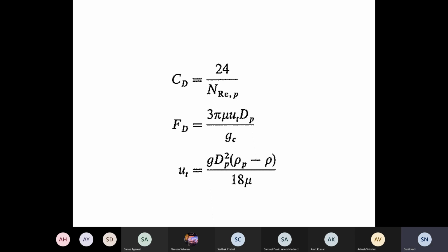And then I asked you to find, at Reynolds number 1, what is the value from the general expression that you get for CD and compare it with the 24 value that you get if RE is put as 1 in this idealized expression for the creeping flow region. CD is equal to 24 by 1. And I asked you to find the percentage error. So these are the two questions that everybody must be able to do.